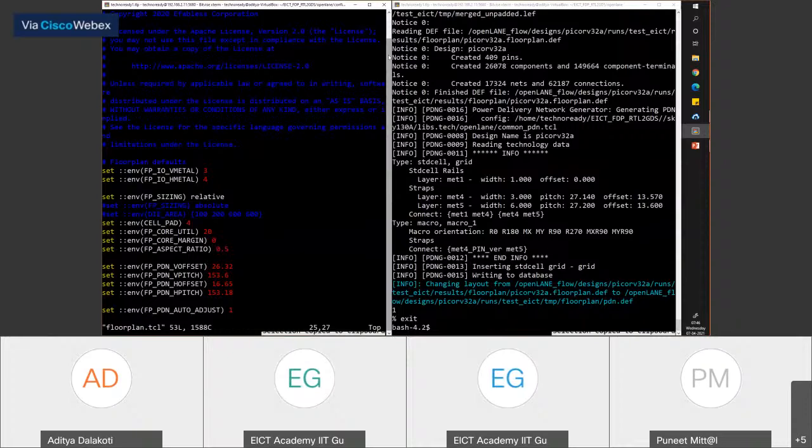Naveen, basically, if you know the cell area, usually a good estimate is you assume it to be around 40-50% of your total die area, because another 10% odd would increase in the CTS. And then in order to have decent routing and flexibility later on, you should not exceed your utilization at the end by more than 50-60%. That is for conventional tools. But for your open source tools, they do not have fancy routers. So it is very hard to hit higher utilization than 20-30% in complex designs at all.